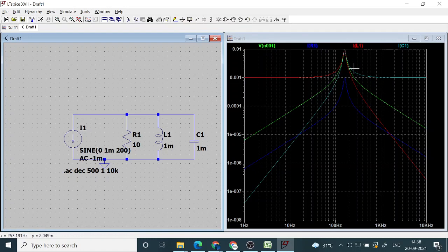The peaking information is suppressed, and it amplifies the variation with respect to decade. Earlier it was seen like 0. It is actually very negligible. If you compare it with 10 raised to minus 5, 10 raised to minus 6, 10 raised to minus 7, they are all very negligible quantities, but still it is amplifying the variation. So that's the difference between the logarithmic plot and linear plot. Okay, so when you want to see large details of small variations, we prefer logarithmic, and also to suppress large variation, logarithmic scale is good.